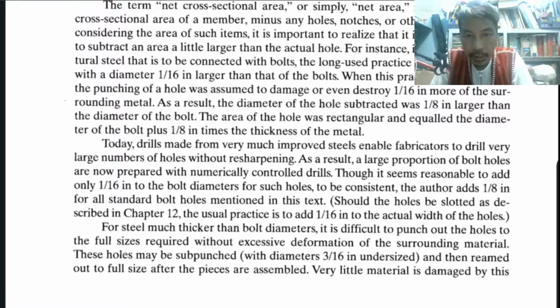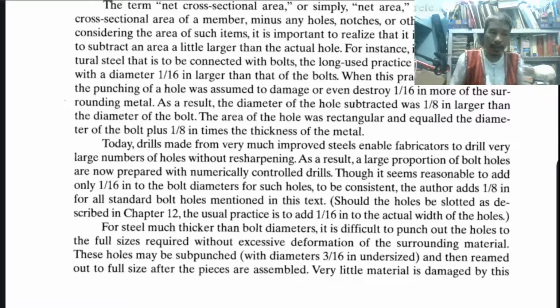Should the holes be slotted as described in Chapter 12, the usual practice is to add 1/16 inch to the actual width of the hole. Okay, that is for slotted holes.